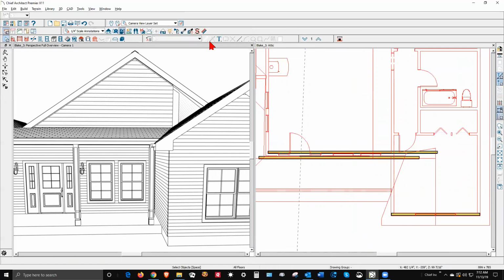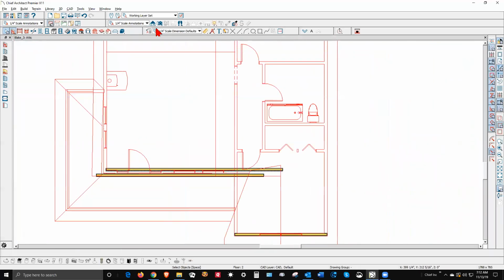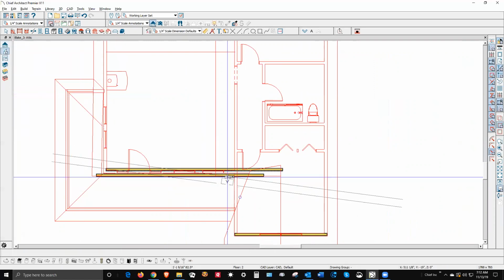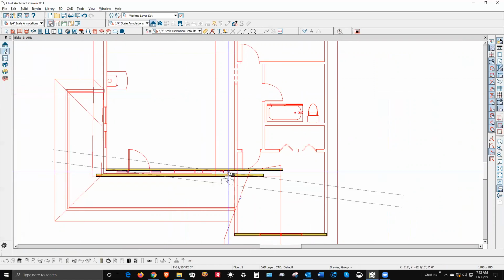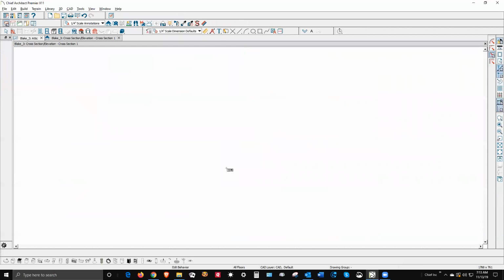Let's see now. I'm going to look at this. I'm going to close this camera. I'm going to look at it in a backflip cross-section camera. It will include just that wall. So your backflip cross-section goes from where you left click on the screen to where you release the mouse, and that's all you see of the model.